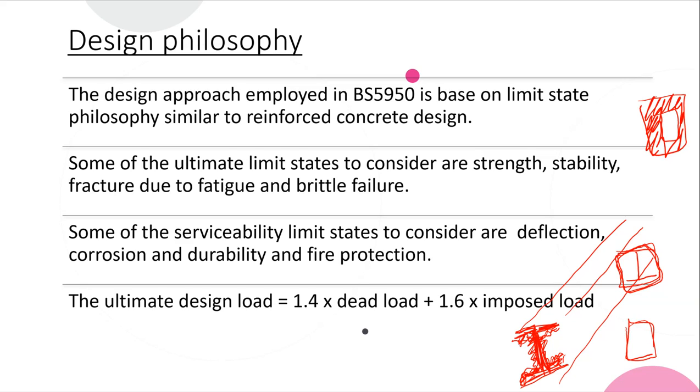Actually this one you probably studied, when you learned theory about steel, how to protect it against fire, but this is what I just explained a little bit, to give you an idea of how to protect against fire and weather. Intumescent paint is like ordinary paint, but a different type of paint that can provide protection against heat or fire. When there is heat, its layer provides a different kind of protection, not the same as normal paint.